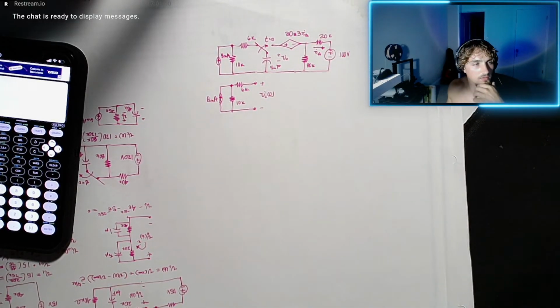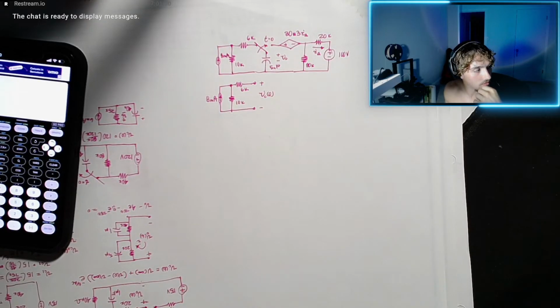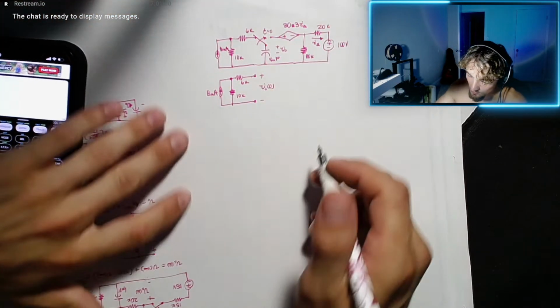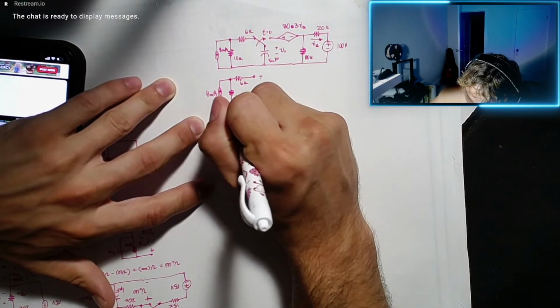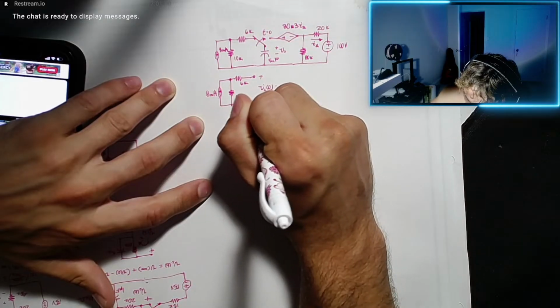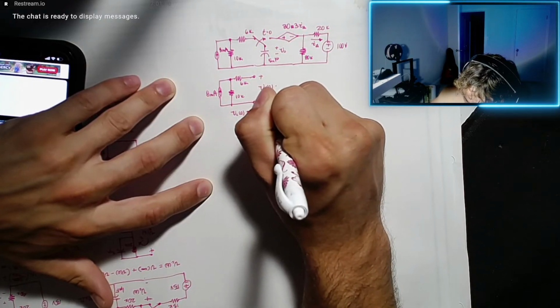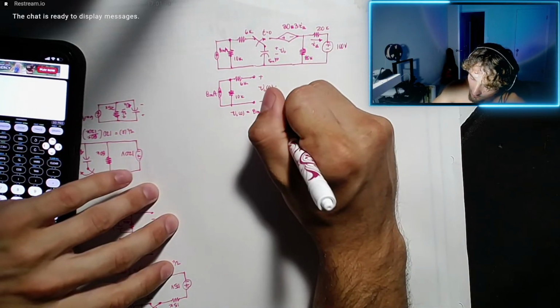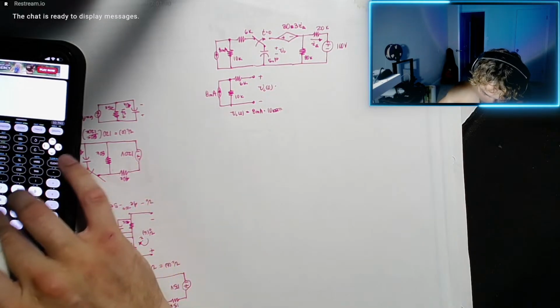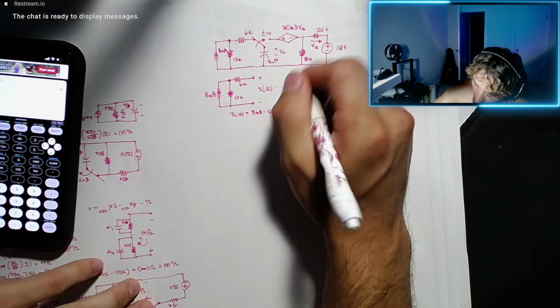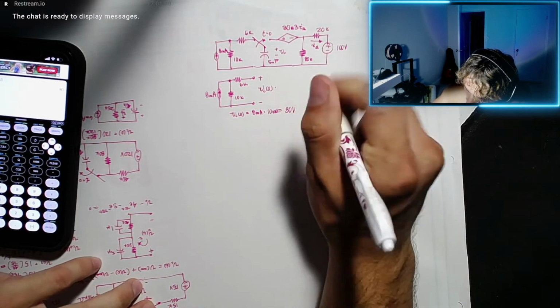So is it going to just look like the voltage developed across the one resistor? Is that what's going on here? That's an open circuit, yeah. There's not going to be any current flowing through this. So after a long period of time, VC 0 equals 8 milliamps times 10K, volts.